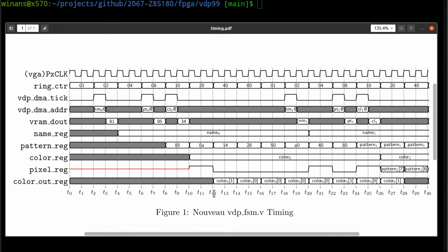So what happens, you'll see here, is that the VGA sync module is generating the pixel clock, and its row and column will be 0 over here at T0. This logic takes 12 whole time periods before it can do what it needs to do, that it should have done way over here if it was going to do it instantly and in sync with the VGA sync module output. But we can't do all this at once. So what I've got, you'll see in the state machine, is a pipeline.